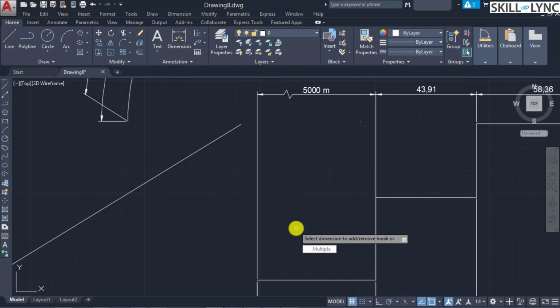This command can be extensively used for dimension lines as well as leader objects, and it can be applied to linear dimensions, either aligned or rotated, angular dimensions, all the radial dimensions, that is radius, diameter, jogged, and arc length dimensions, ordinate dimensions, and also multi-leaders, that is for straight lines or spline leaders.